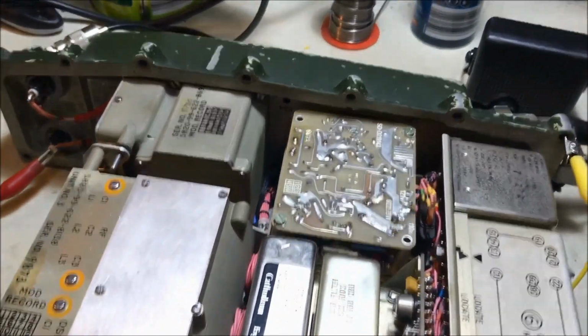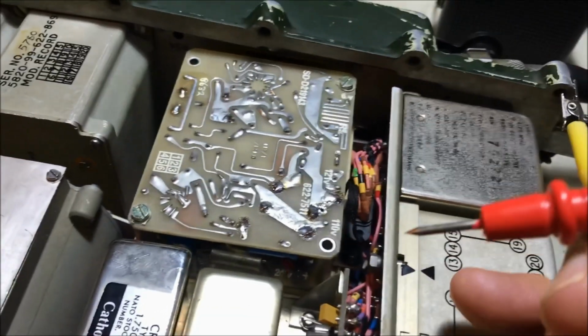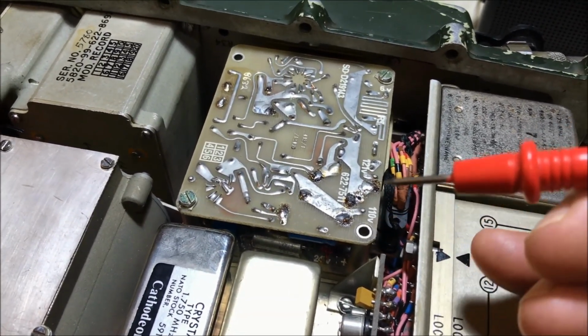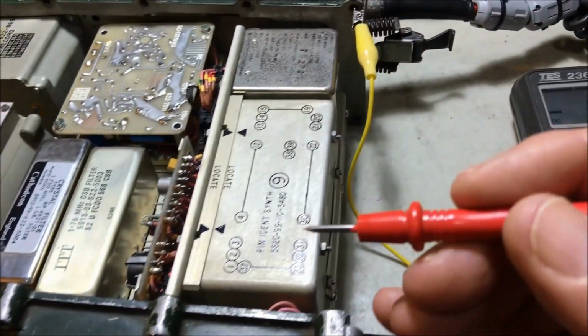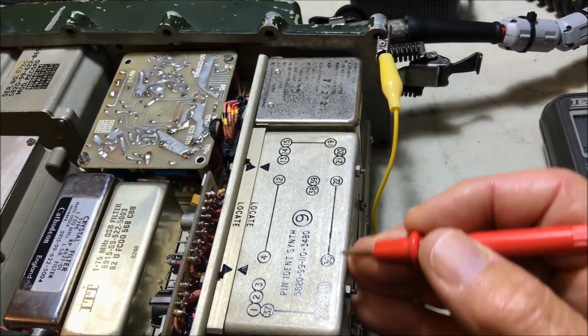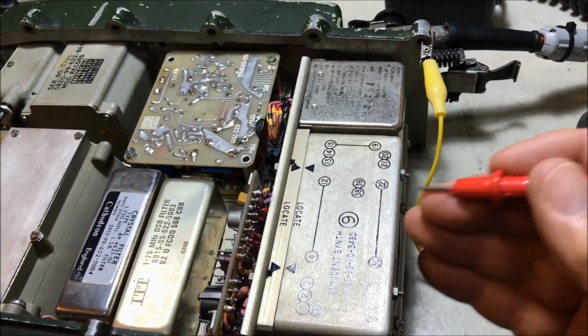Okay, we're back in the workshop. I mentioned before about the 110 volt supply being the main issue when it comes to wobbliness, so we need to make sure that that's all right. As I suggested, I changed the capacitors on the power supply, and here's the synthesizer. On the top board, just under there, there are two 10 microfarad capacitors. They're the ones that have to be changed.